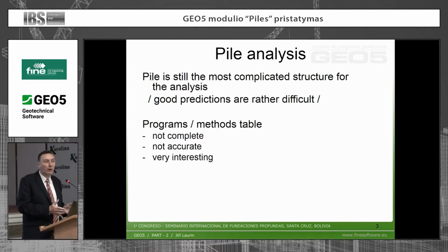For piles, you have one method, bearing capacity is 1,000, second method, bearing capacity is 2,000, third method, bearing capacity is 5,000. The difference in the results is pretty high, and it usually depends on local experience, because you should know your soils and type of construction, and the geological survey, the data that you have about the soil and from which you compute the bearing capacity.